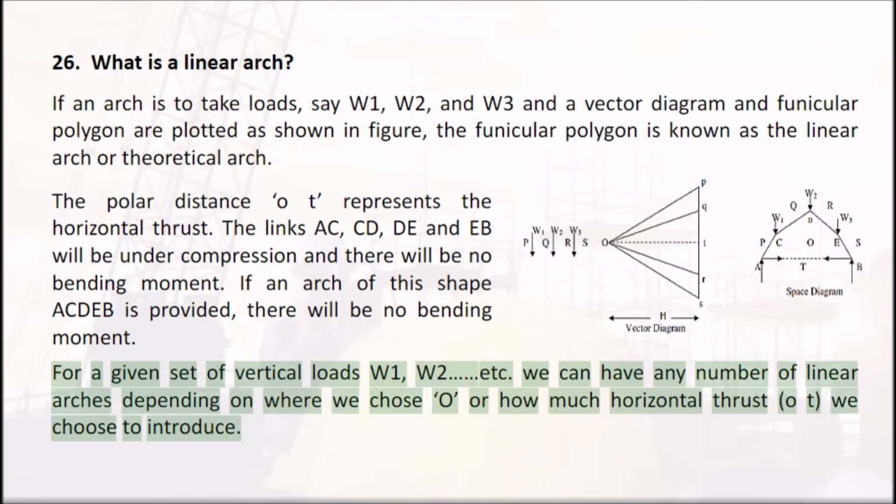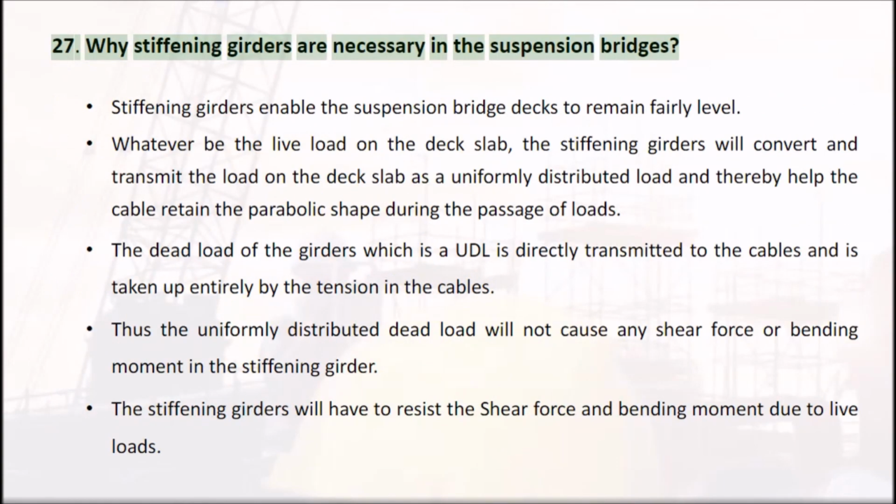For a given set of vertical loads W1, W2, etc., we can have any number of linear arches depending on where we choose O or how much horizontal thrust, OT, we choose to introduce. 27. Why are stiffening girders necessary in suspension bridges?